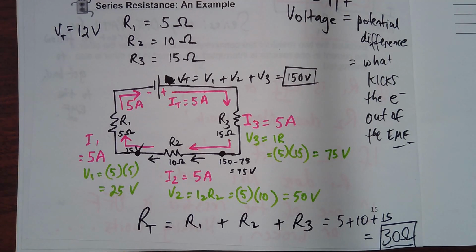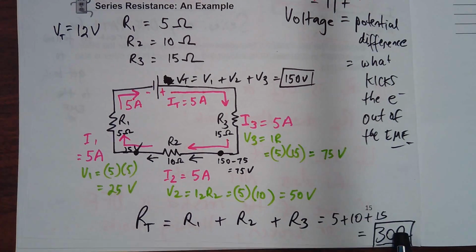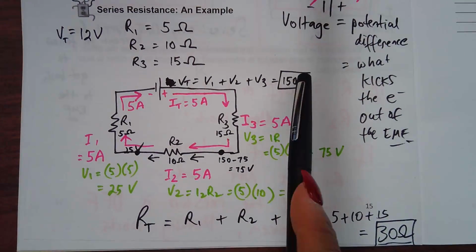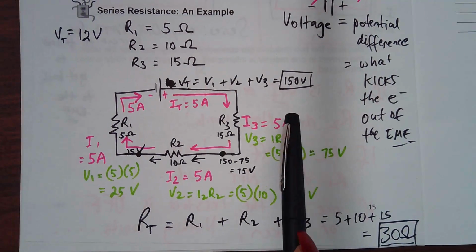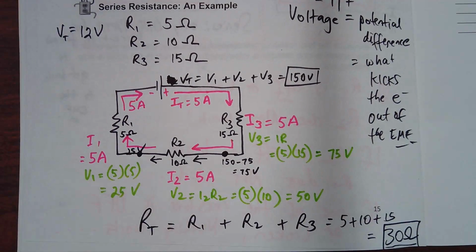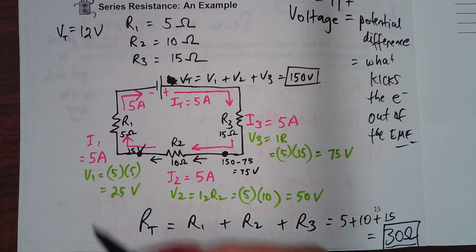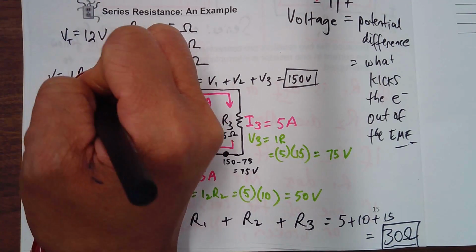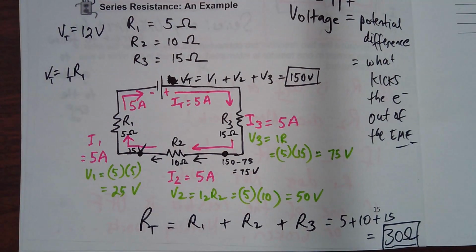So now, with our example, we know the individual resistances, which are given, and we've just calculated the total resistance. We know the individual volts and the total volts, and we know the individual current, which is the same as the total current in a series anyway. If you go V equals IR and you want to know the total, you have to use the totals of everything.